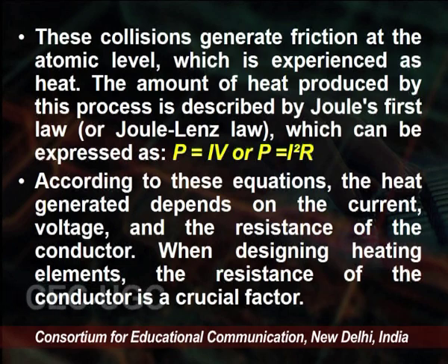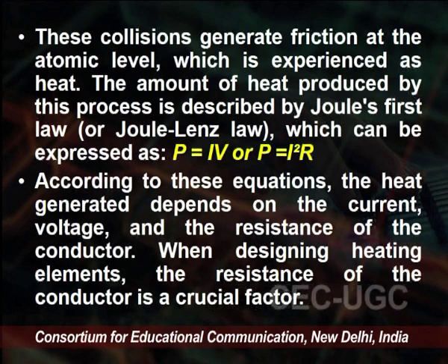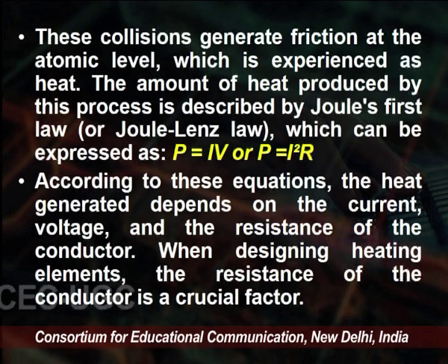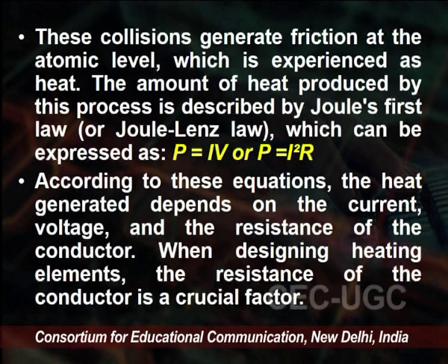The amount of heat produced by this process is described by Joule's first law, also called the Joule-Lenz law, which can be expressed as P is equal to IV, or we can write it as P is equal to I square R. That is the amount of heat generated.